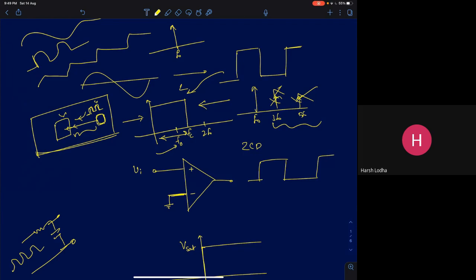Once the sinusoidal waveform enters a chip, because it's a digital circuit that operates on binary levels, you'll have to convert it back to a clock signal or a square wave signal. So that's another application where sine wave to square wave converters are often used.